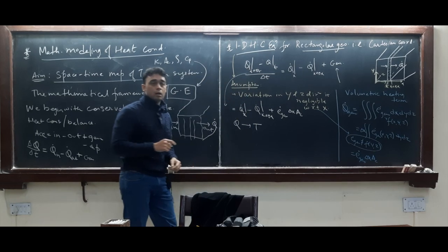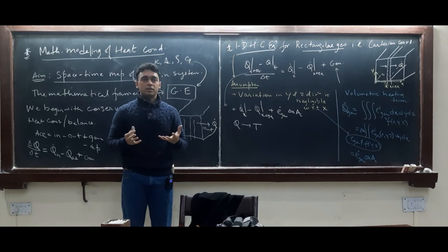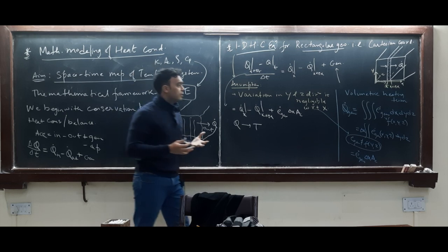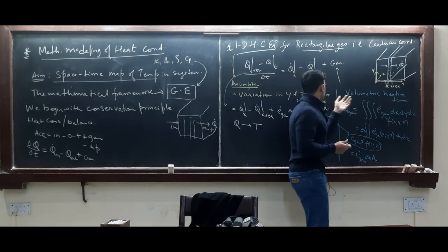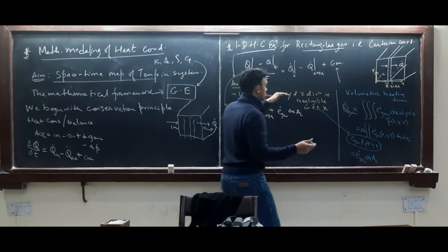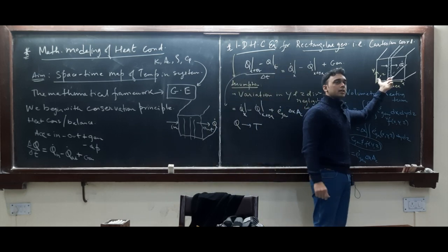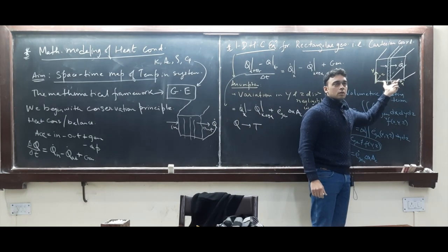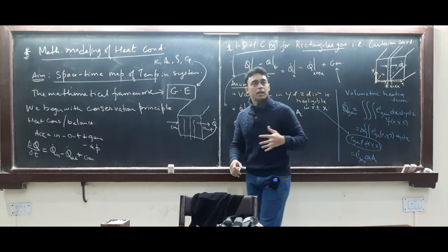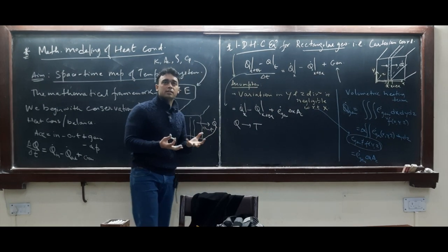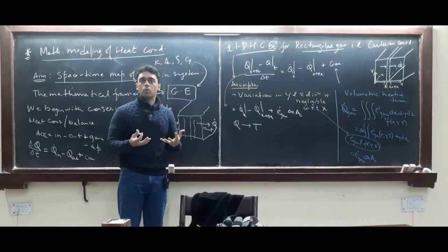C. Specific heat. We use the idea of sensible heat. We assume one more assumption, you can add it in your copy, I don't have the space to write, that the material does not change phase. It's solid. So any heat that is given will change the sensible component.